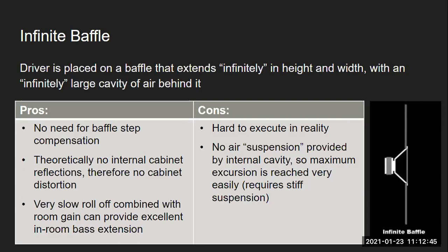Of course, that's not really a thing. Over a certain size of volume, depending on what the driver is, I think it's when you reach 5 times or 2 times the VAS, which is a parameter used in measuring speakers, then it starts acting as an infinite baffle. So the cool thing about an infinite baffle is that you don't have to compensate for something called baffle step.